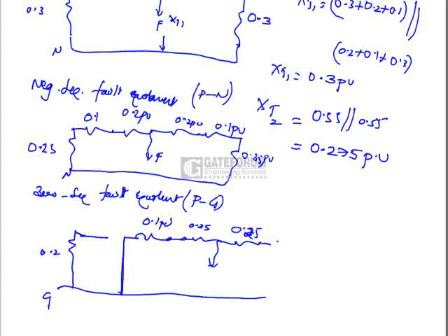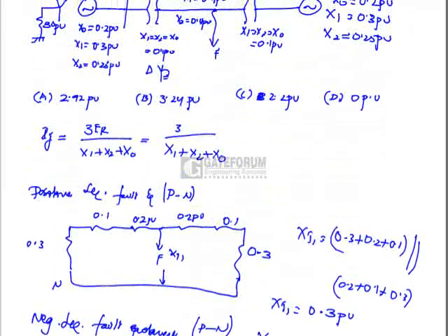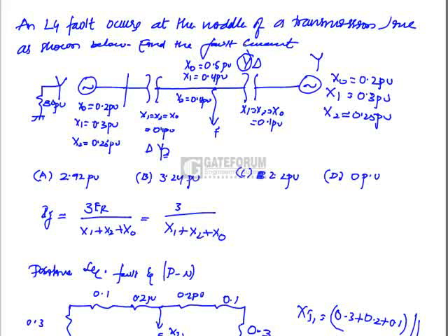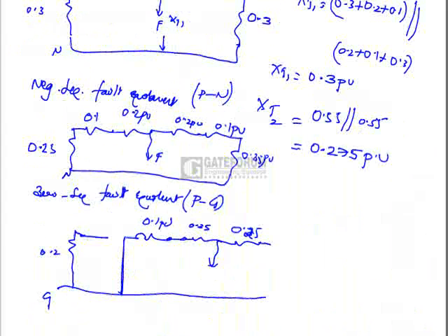After that we have a connection of star by delta. Okay, since it is star, winding is not grounded here. Okay, in the figure he has given this one as star by delta. Since this transformer is not grounded, we should not operate the series switches. Okay, so this is open circuited.